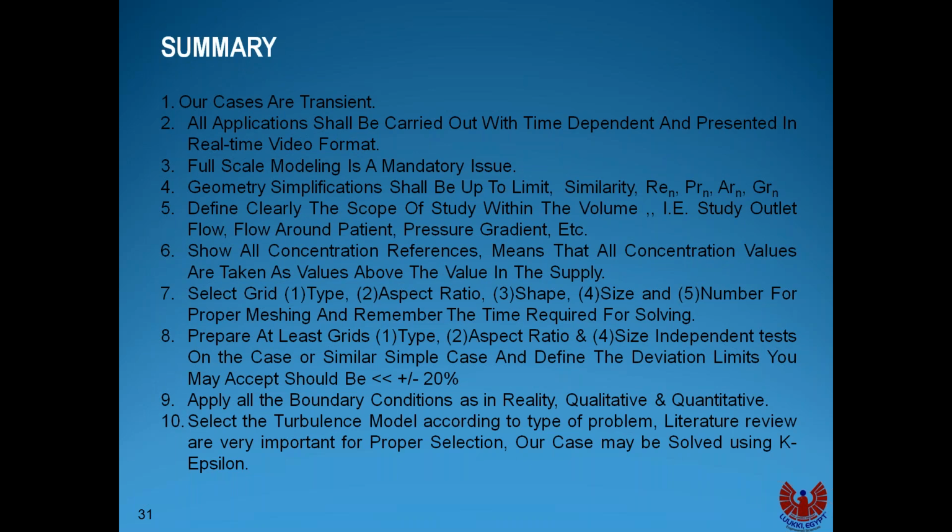After that, you have to declare in this report that all the boundary conditions shall be considered typical of reality. We cannot say in any case study like this, we can consider this wall adiabatic, this is constant pressure. No, we have to follow the reality, because if you give the computer bad data, he will get a very bad result.